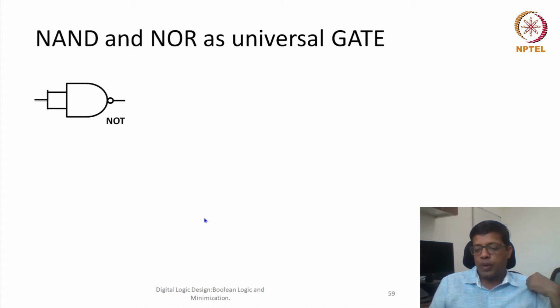So this looks a little confusing. Initially, when we started our course, we said that the Boolean algebra would be operated upon by three basic operators, that means OR, AND, and NOT. So now we are saying that only one operator is sufficient, that is NAND. So why is it possible? Because NAND can essentially be used to represent NOT gate as well as OR gate as well as AND gate. Why? Because of the properties which we have discussed in our previous slide.